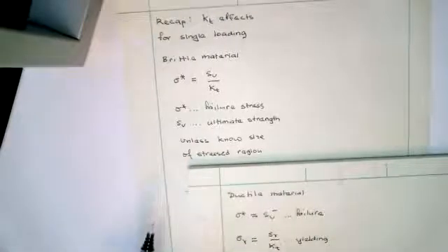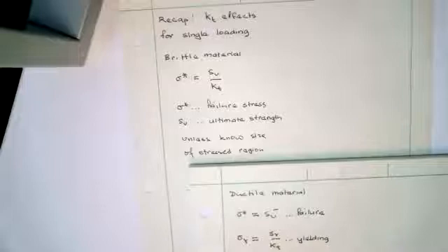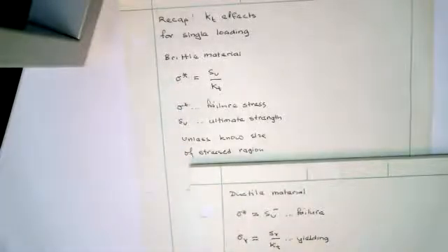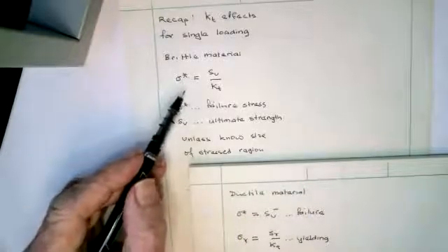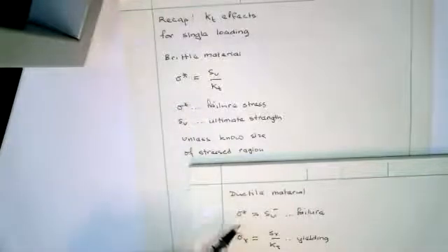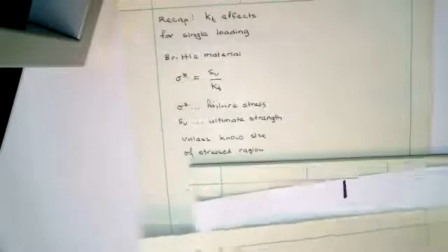So while the book does say these things are very important for fatigue, they're also not insignificant for single loading. But typically, you don't do brittle materials with single loading. You try to avoid loading brittle material. On the other hand, these C clamps are built for single loading, and this would definitely screw up your design. Any questions on that?